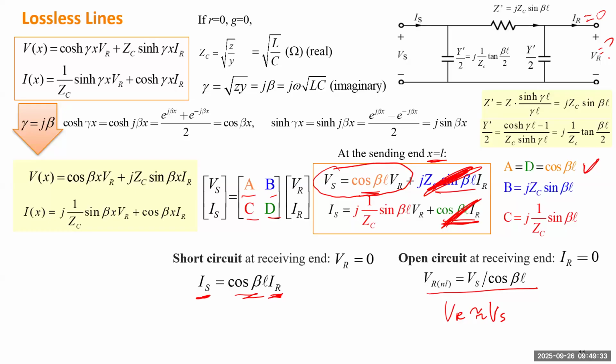So for the first contingency, we expect the factor to be really small, such that even if you have a short circuit on the load, the source is not impacted. But for the second contingency, we hope this factor to be large, close to 1, such that the load voltage can maintain the same voltage as the source voltage. So let's try a different value.